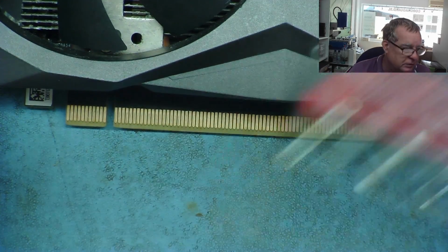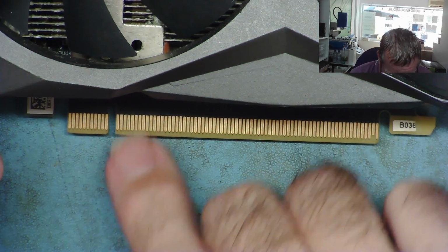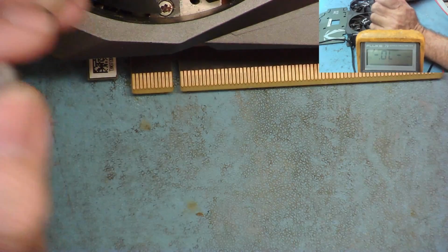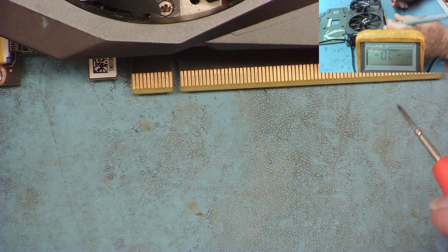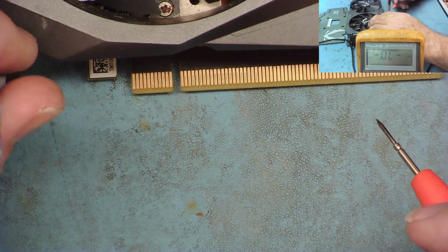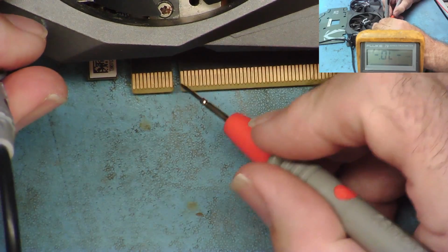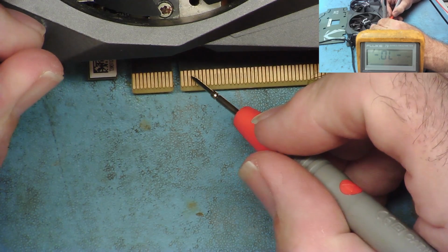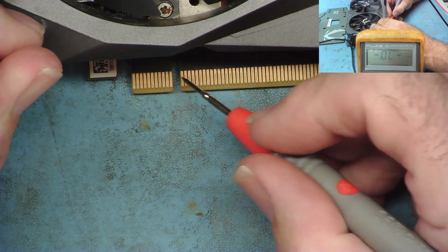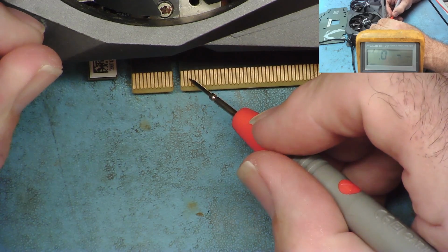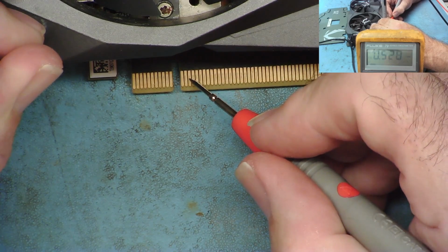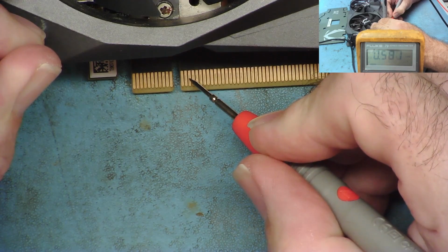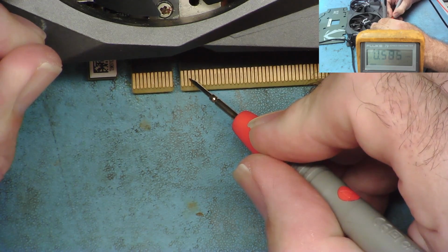So let's see straight away if that's happened, and the way to find out is just to check on the PCIe fingers. We have the multimeter in diode test mode, so I'm going to test from ground with the black lead to the PCIe. On this side, I'm interested in the third and fourth finger after the notch. So 1, 2, 3 is reading 4, but as it settles down, 5.6, 5.7. Normally they don't climb up like that.